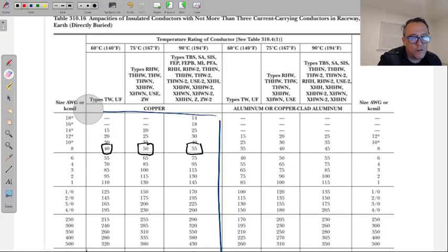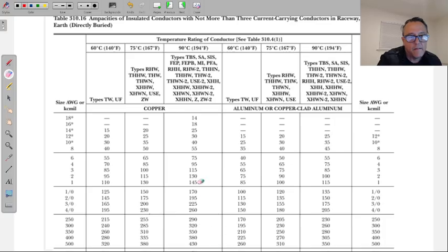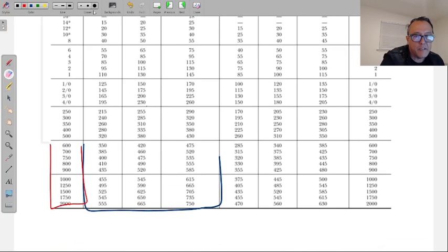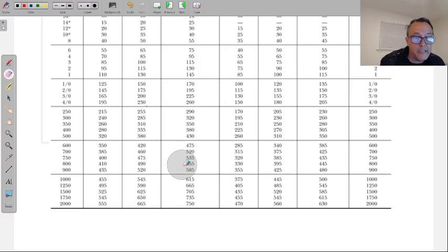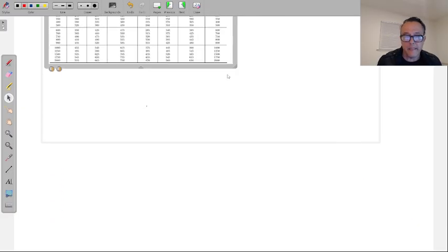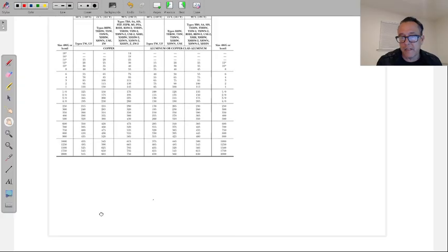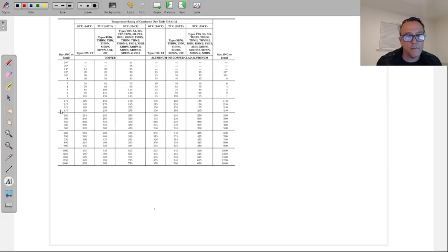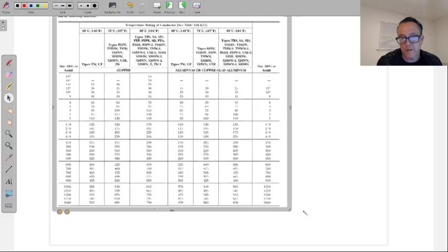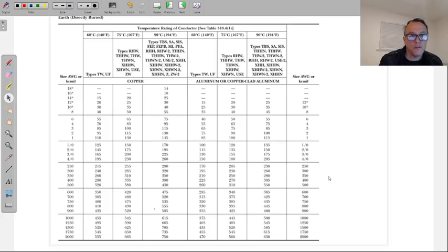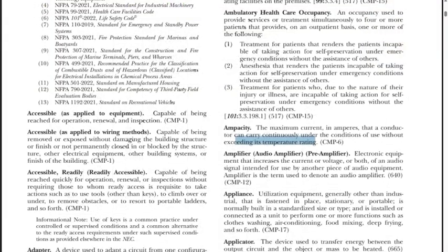So the wires can also effectively lose their ability to hold the amperage they are said to be able to hold if we put too many wires into a conduit. There's a whole section that walks us through this, and you'll get to that in code B, where you'll size wires and be given adjustments to make based on the temperature around the wires and how many wires are in the conduit. But it starts here with an understanding of that word, ampacity.